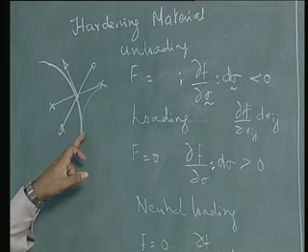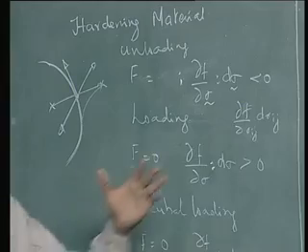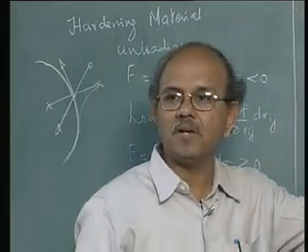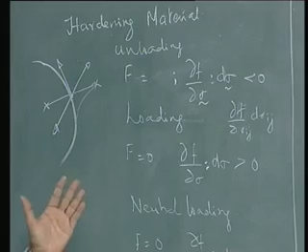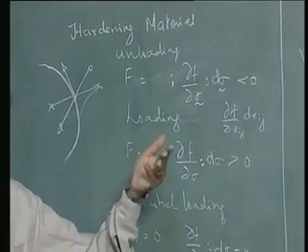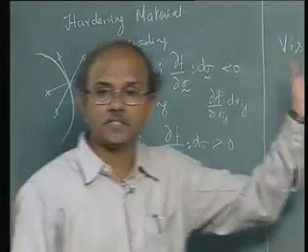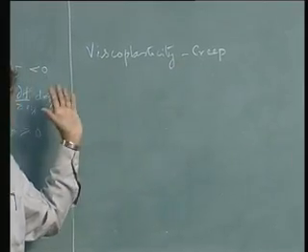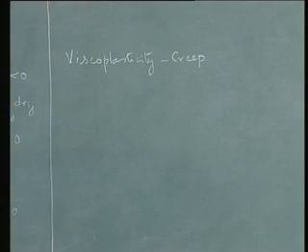Or in other words, as t tends to infinity, when times are very large, the solutions of viscoplastic problems would be the same as that of the plastic problems. So it is possible that you can do a finite element analysis for a material with the assumption of viscoplasticity, look at the solution as t is very large, and say that that is also a solution for a plasticity problem.